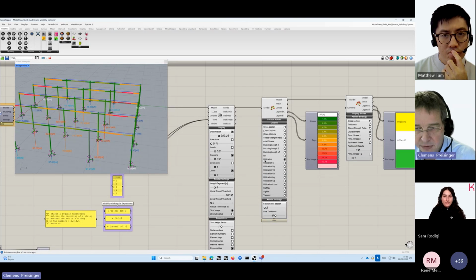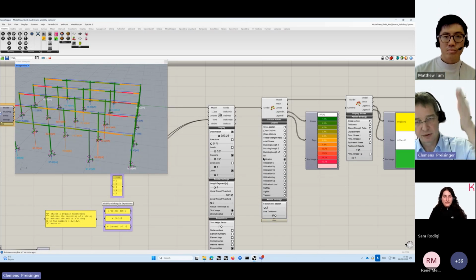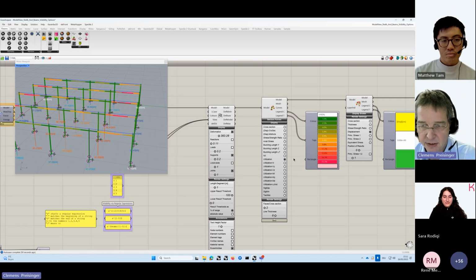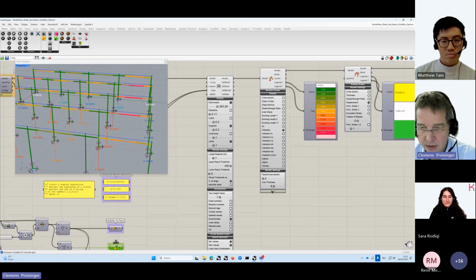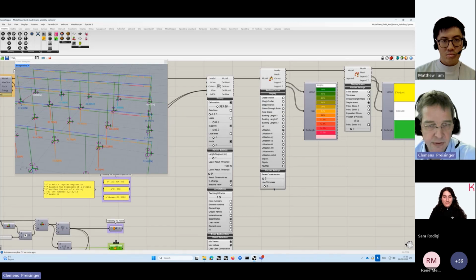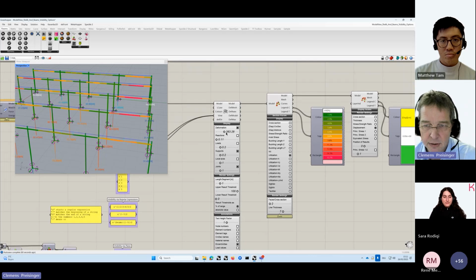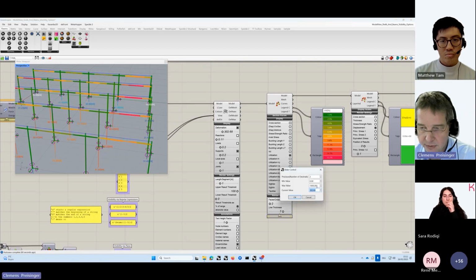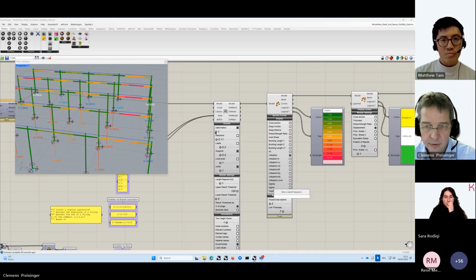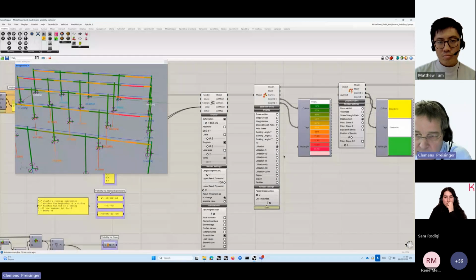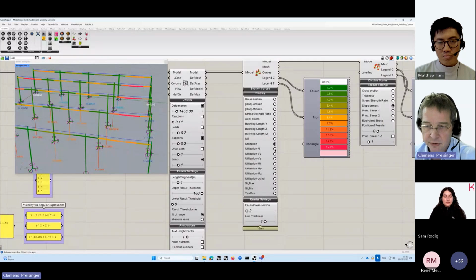So for example, a utilization: there's one value per position on a beam, and this is now rendered as a colored line where you can increase or decrease the thickness if you want. You can also double click here, increase the scale, and see how it deflects. So utilization of the element, the total one, then according to normal forces, shear forces, and so on.